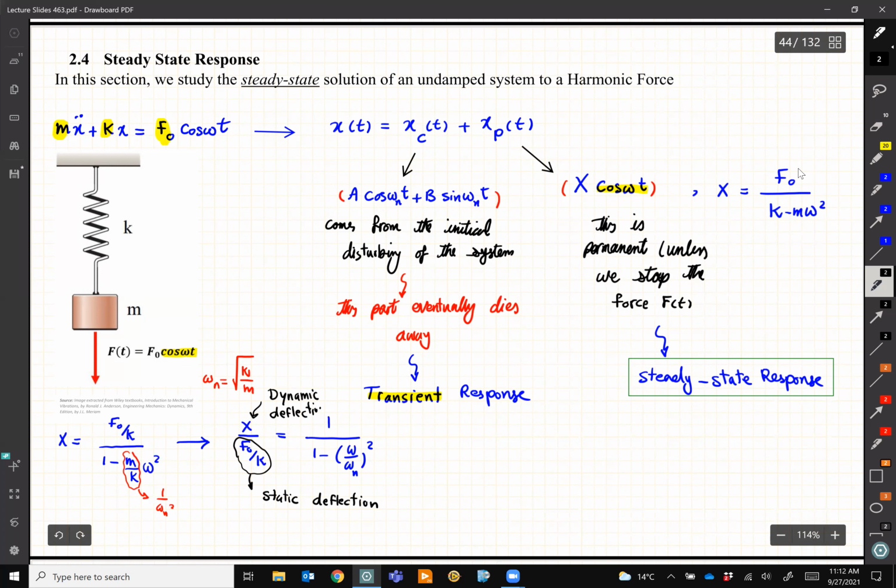In a system, when we want to analyze them, we are interested in this ratio, right? Because we say, okay, if the system wasn't static, we probably have a reasonable amount of static deflection if I apply this force like a constant. So this ratio, which is an important factor for us, we call it M. So M is 1 over 1 minus omega over omega n squared.